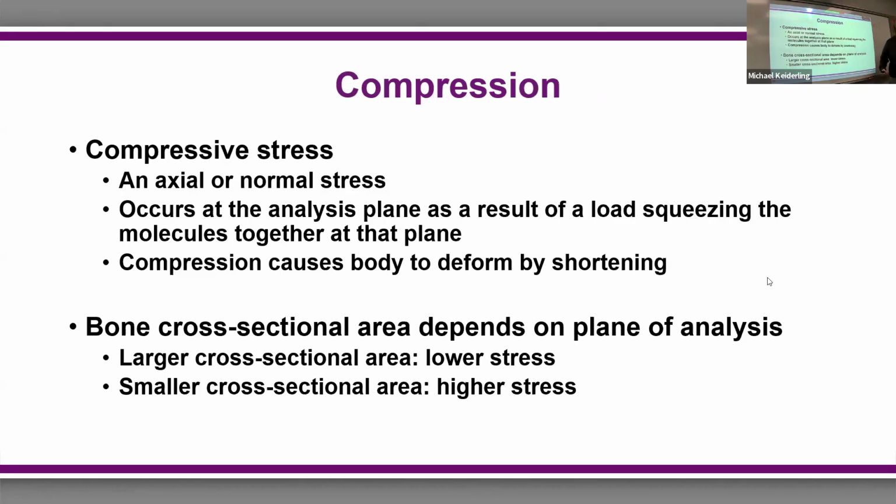Now, compression is kind of the opposite of tension. Tension is stretching, compression is squishing. It's also an axial or normal stress. It occurs at the analysis plane as a result of a load squeezing the molecules together at that plane. And compression causes the body to deform by shortening. It gets shorter.